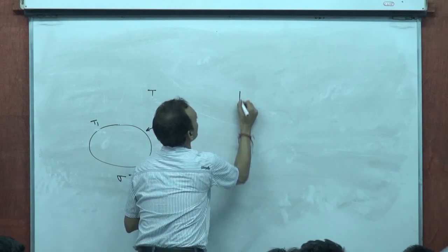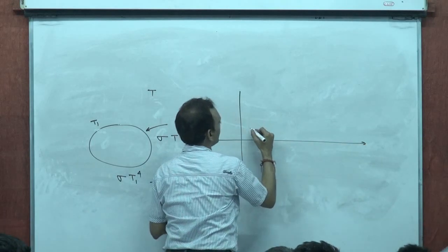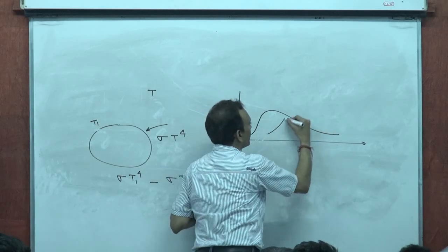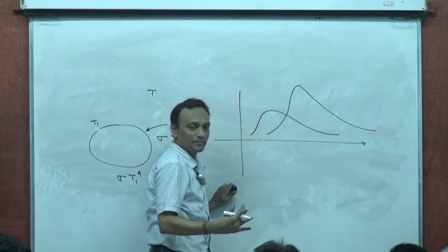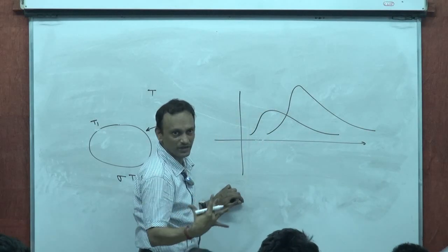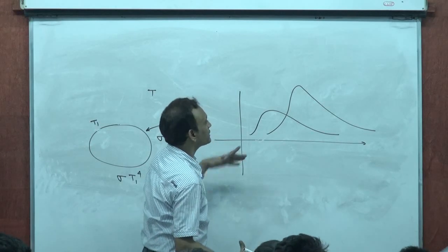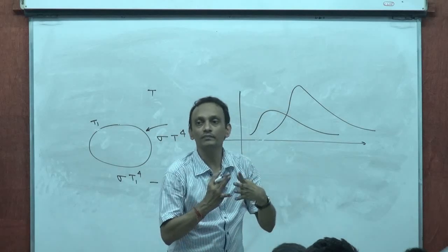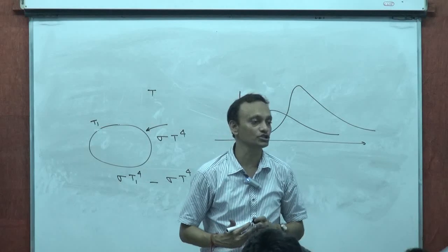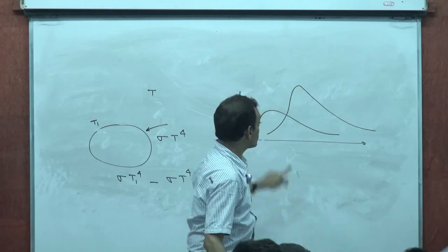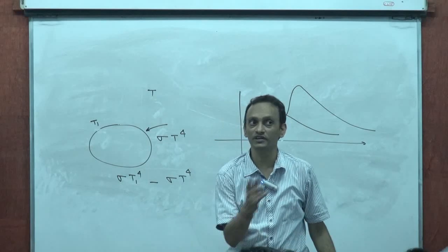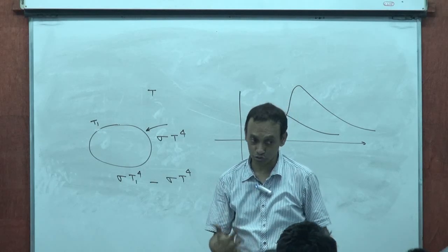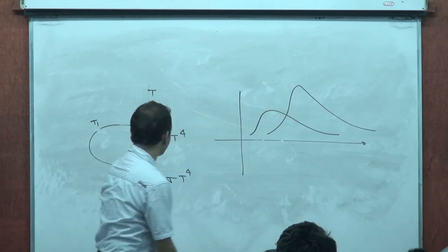So the radiant tubes that are modeled and created are based on this premise. They would tell you, well, wet paper has this characteristic, and the hot radiant tube, which is at a high temperature, will have this characteristic to dry up the paper. So what they would look at is, they will try and match these bell curves to the extent they can, so that there is optimum and best utilization of heat emitted by the radiator. So this is the major problem of radiant heat transfer, where they have to match the emission and absorption characteristics of the entities involved. So this bell curve has to be taken care of.